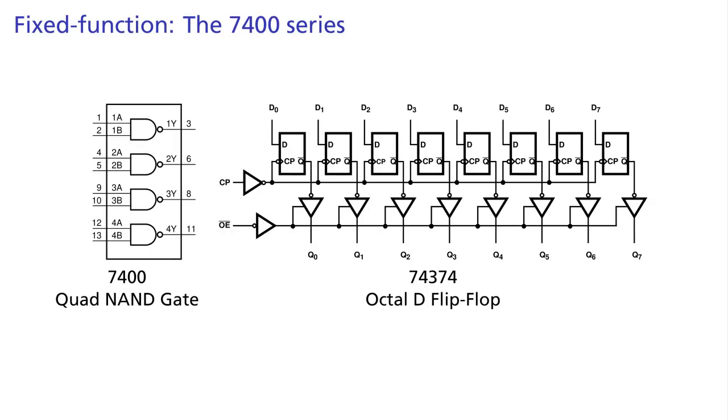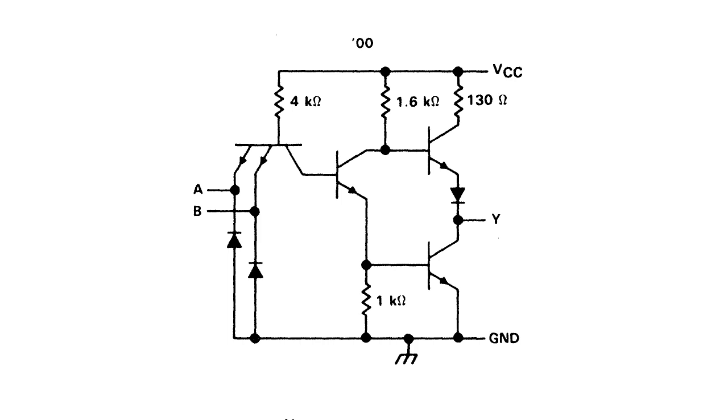These 2 chips are from the so-called 7400 series, which TI and others have produced since 1964. There are now a few hundred different 7400 series chips. They never got much more complicated than this. The original TTL circuits, or transistor-transistor logic, that these chips were implemented with has long been obsolete, although you can still buy chips from this family today for repairing older equipment. Today, this family is implemented in over 30 different logic families, with different power consumption, speed, and voltage levels.